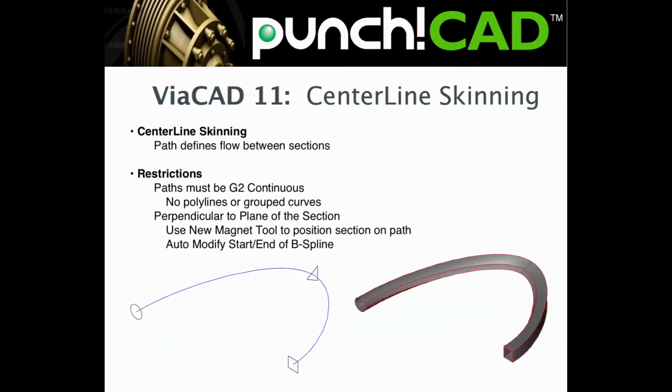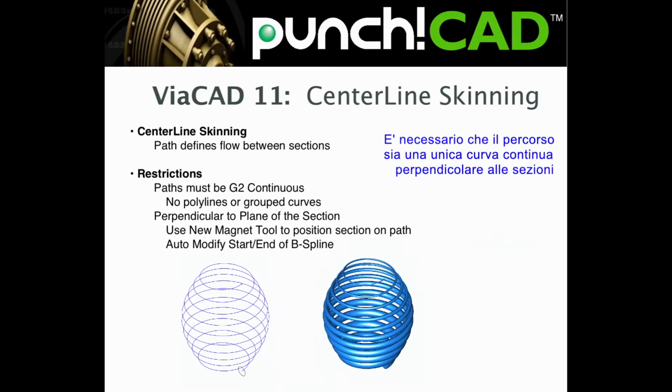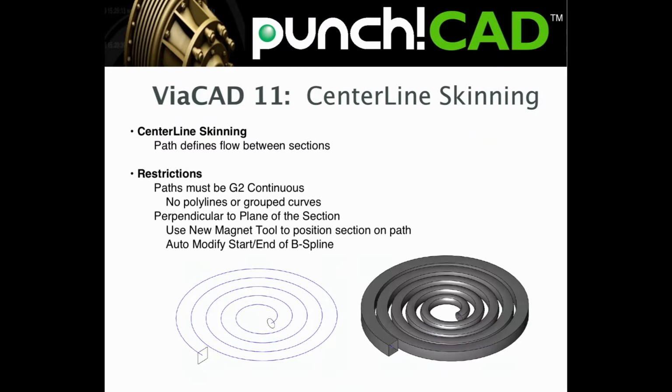The path does have some important restrictions. One, the path must be one G2 continuous curve. This means there are no polylines or grouped curves as part of the path. And two, the path must be perpendicular at the section intersection. I'll demonstrate this later in the video to show how you can accommodate this restriction. Let's go ahead and demonstrate some examples of centerline skins.